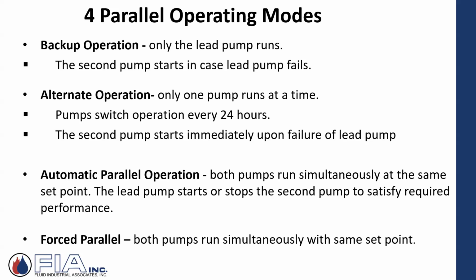This is a much more common alternate operation. Only one pump runs, but it's switched. So the lead guy switches every 24 hours, equal runtime. And then the second pump would also start immediately upon failure of the guy that's supposed to be running. So that's where maybe you start to eliminate that pump sequencing third-party need. It's built in.